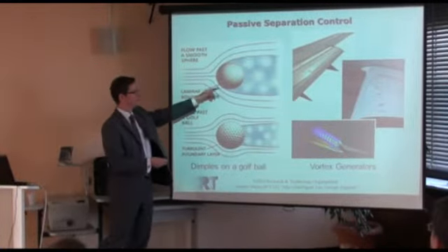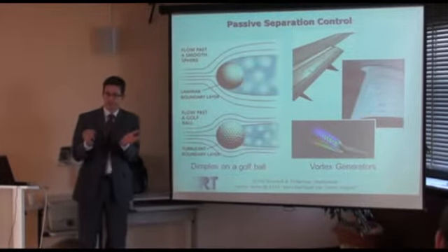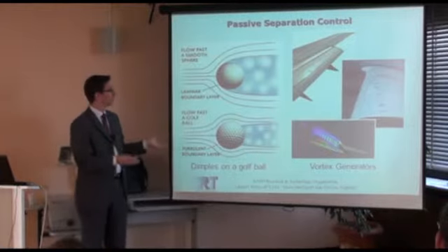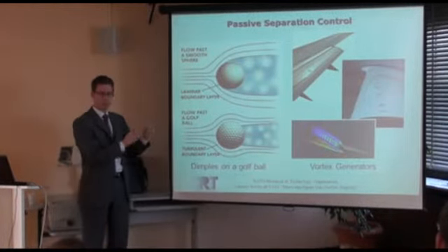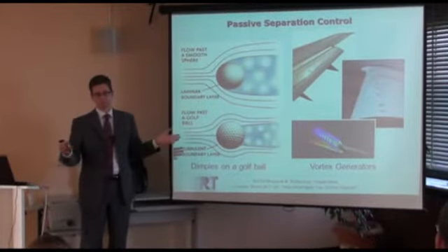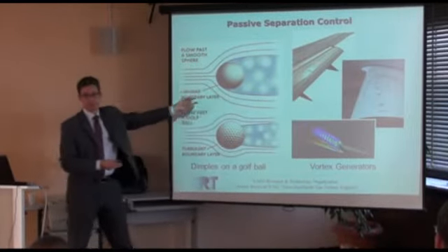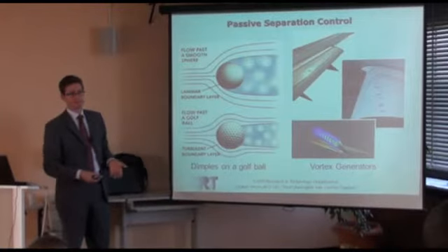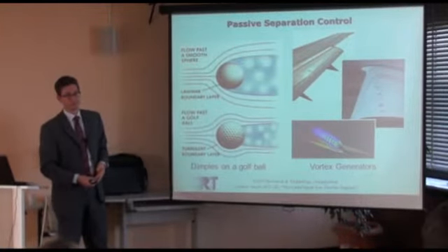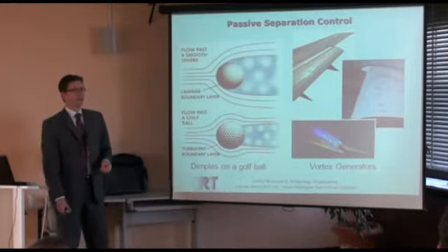In laminar flows, there's very little momentum in the fluid which can evolve because basically there's nothing happening. So the laminar boundary layer gets thicker and thicker and thicker, until it detaches. And if nothing happens, you could say that nature forms its shape itself. You typically lose some energy due to the turbulence, but you gain a pressure recovery due to the better attachment of the flow. So it's a trade-off in introducing vorticity.